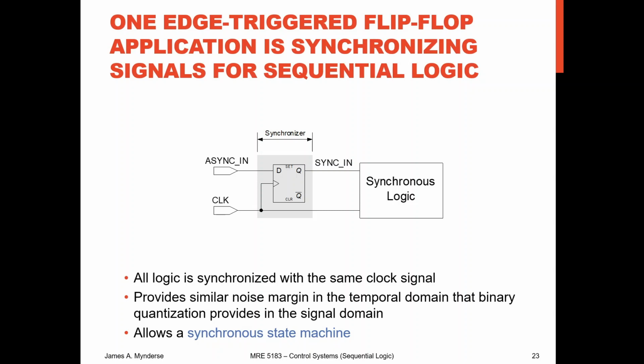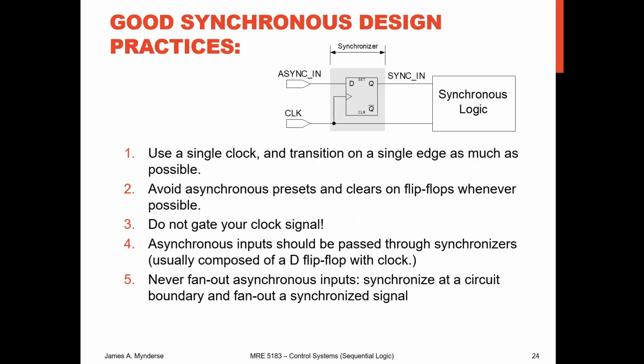The reason we might want to do that is if everything's synchronized to the clock, then we have fewer possibilities of error. This is kind of like the noise margin we dealt with previously, but noise margin is at a voltage, and this is more in the time domain. So it does make sure that we have fewer errors. I would say it's always nice to synchronize your inputs. So one clock signal, synchronize all of them, synchronize them all before they come into the logic.